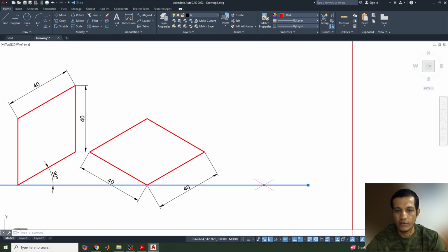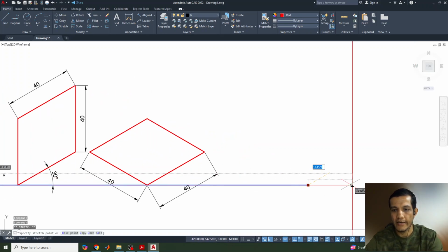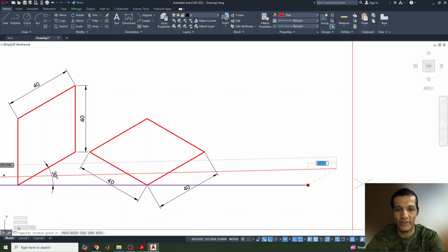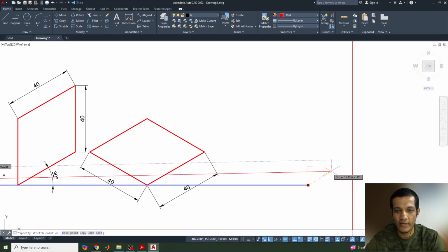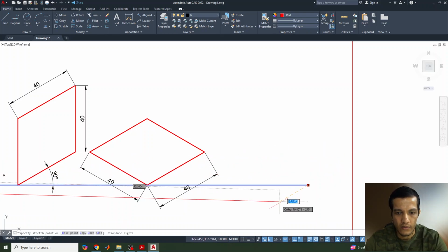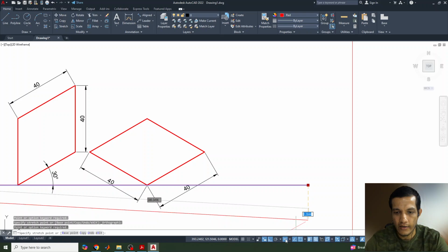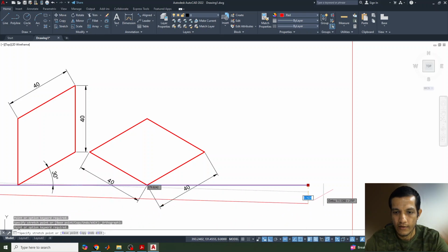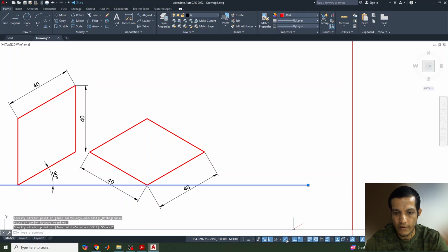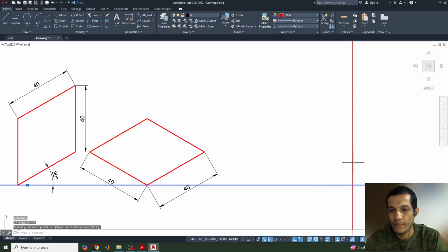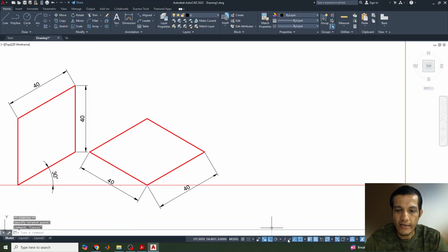Now see, we'll just extend the line. Now see, it is not moving horizontally, it is moving only in top because iso top was selected. So what I will do, I just unclick this one and click it again. Yeah, now it's clear. So I just extend this line, and this boundary also I can extend. Now again I'll change this one.